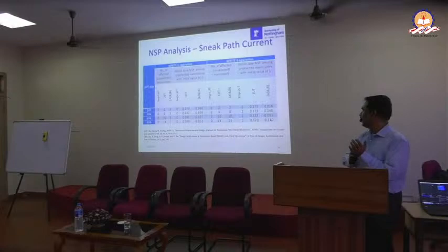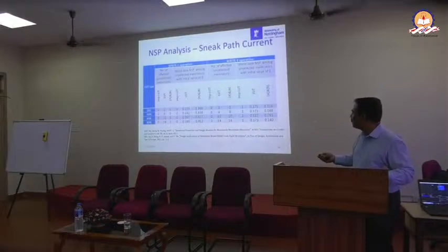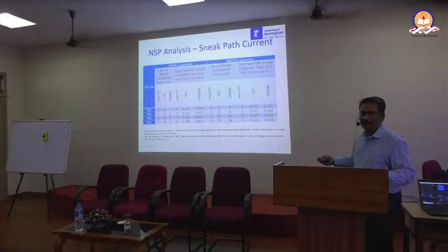Then what we analyzed is, we took different memory string sizes, the array size, from 2 by 2 to 8 by 8, and we performed this across different methods. This is our improved LUT, the second LUT. This is our first LUT, the first model, and the previous works. So what happens is, if you perform the write 1 operation, the number of affected memory strings is almost 0 in all the array sizes.